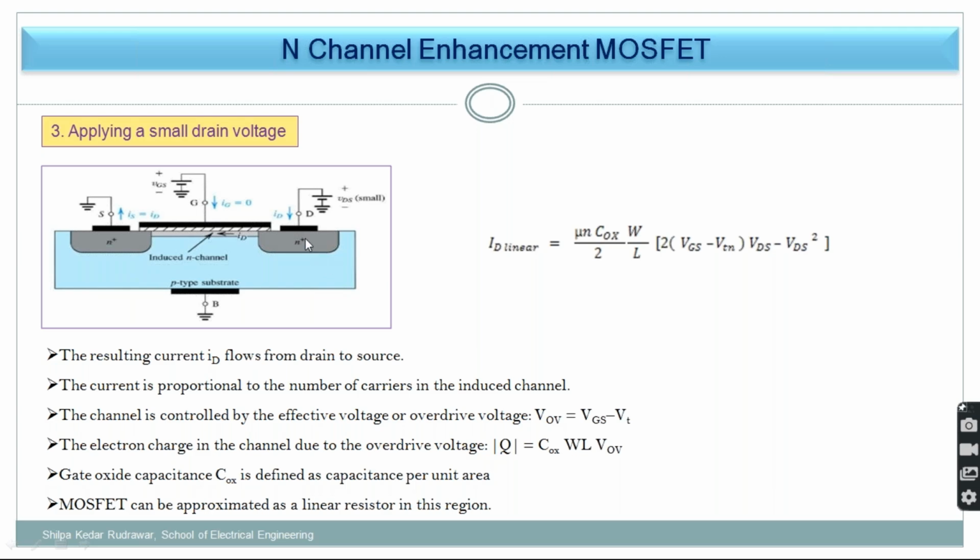As you know, this is a PN junction diode. I have already shown the diagram. So does this PN junction diode become forward bias or reverse bias now? Just think, because this is the N type material and this is the P type material. P is already connected to ground, and this N is connected to positive, meaning this is becoming reverse bias. And if it becomes reverse bias, the depletion region increases, as per your previous knowledge of semiconductor devices. That's why at this point the depletion region increases, which is shown over here.